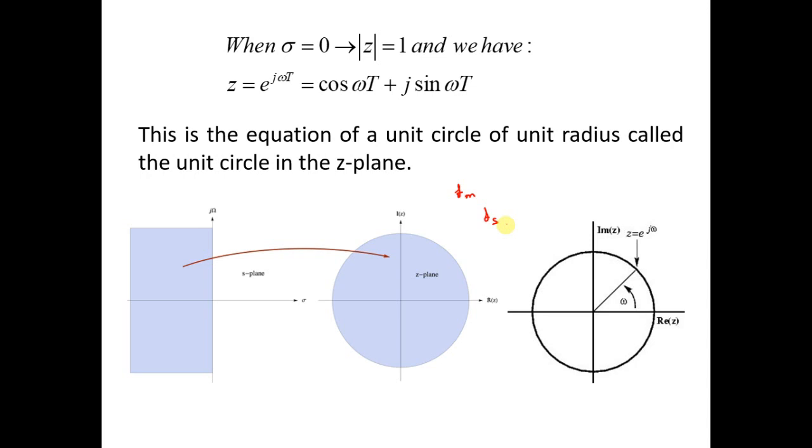There is a criterion called the Nyquist criterion, where we say Fs is greater than or equal to 2 of Fm. So since we have both the Fm and Fs, the Fs would be the highest here. So Fs assumes the highest position.